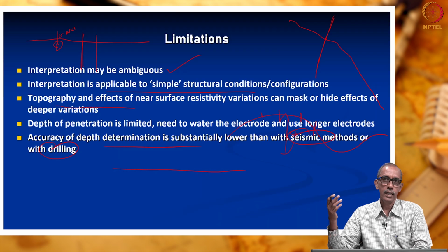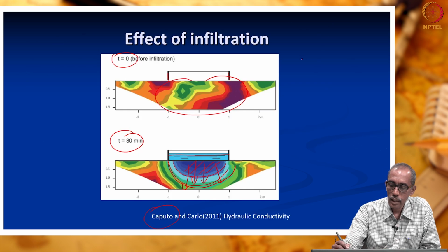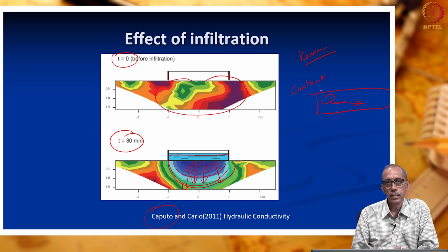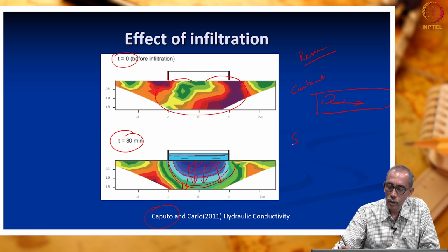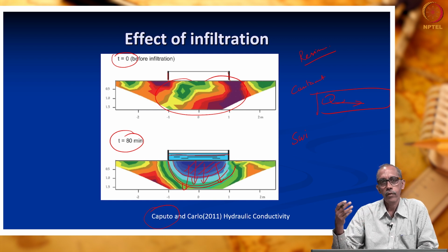So, in this lecture we have seen what the electrical resistivity methods are and their specific applications. First we saw how a contaminant plume migrates below the surface of the earth. We could understand the migration by repeatedly measuring the electrical resistivity survey. Then we looked into seawater intrusion, and how it was deciphered using an electrical resistivity tomogram.